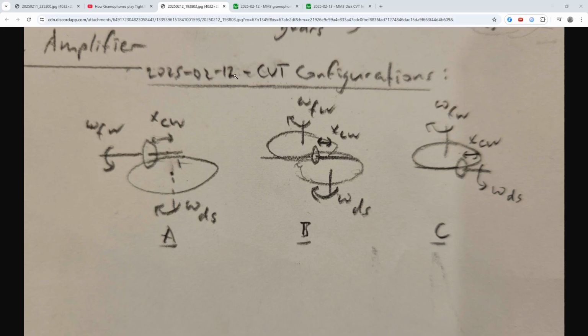One thing to note is that there are actually other ways to arrange a wheel and disc CVT. So instead of having two discs sandwiching the control wheel, we can have just a lower CVT disc with the control wheel connected to the flywheel, or we can have it the other way around. So in this case, we are only controlling the lower bound of the speed using this disc, while here, we are only controlling the upper bound.